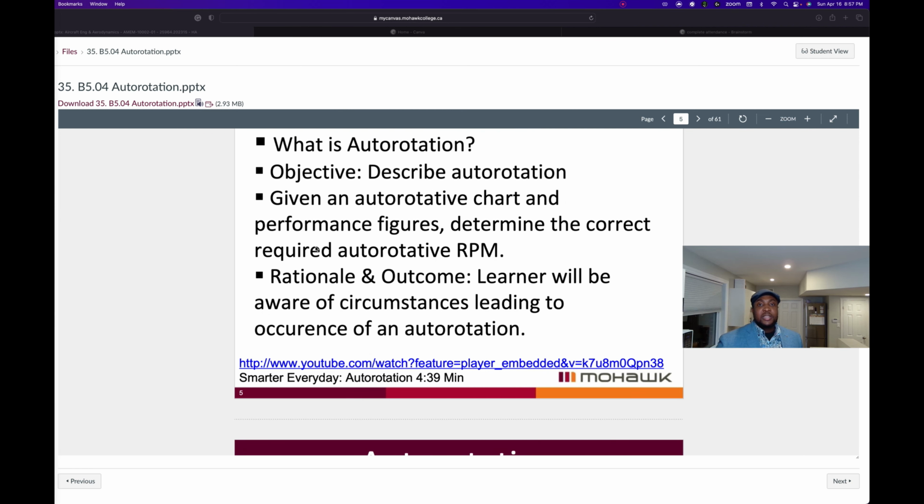The rotor continues freewheeling as the helicopter descends towards the ground. The rotor's speed is conserved during this descent and used approaching the ground to slow the rate of descent to land softly. During autorotation, control of the helicopter can be maintained throughout the descent, allowing for safe landing.